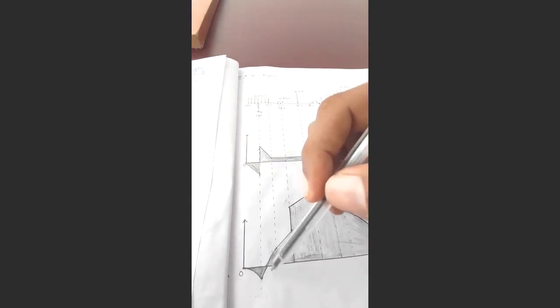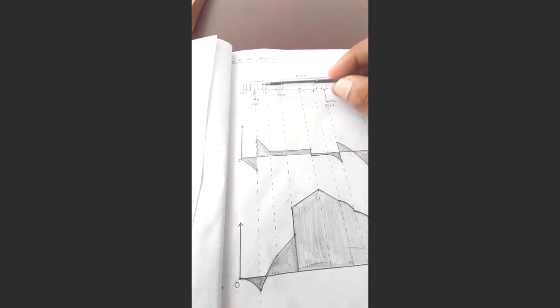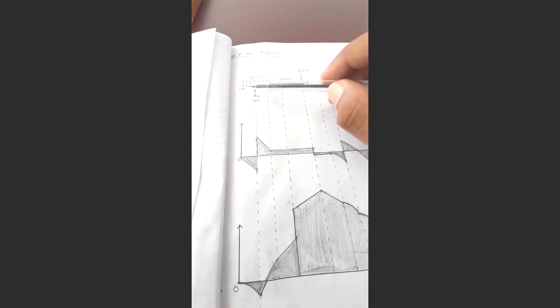Now let's consider the sketching of the bending moment diagram. We are going to sketch it with respect to the sections that we have considered in the calculations. First, consider the section AB. For the section AB, the general equation for the bending moment is -15x squared, which is a second degree curve. The bending moment at the lower limit is 0, higher limit is minus 15. First of all mark that: 0 and minus 15.